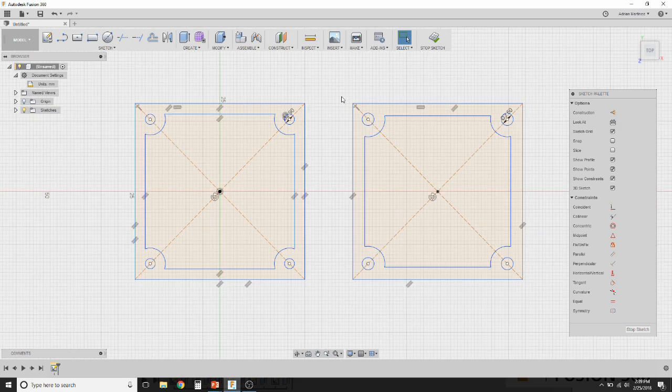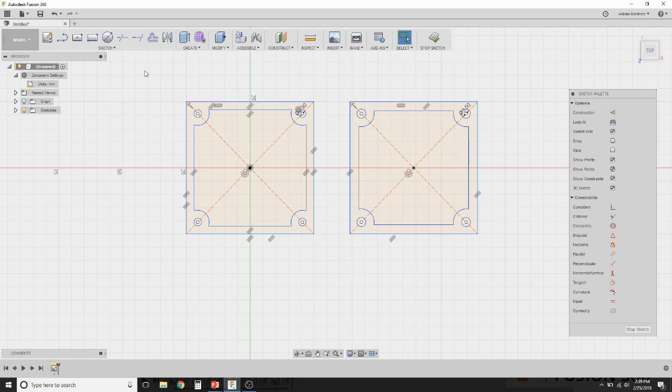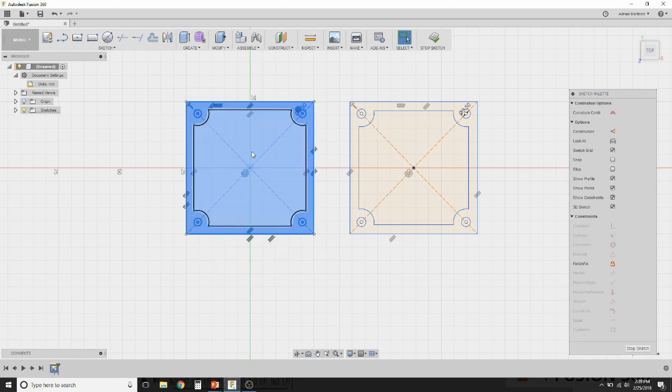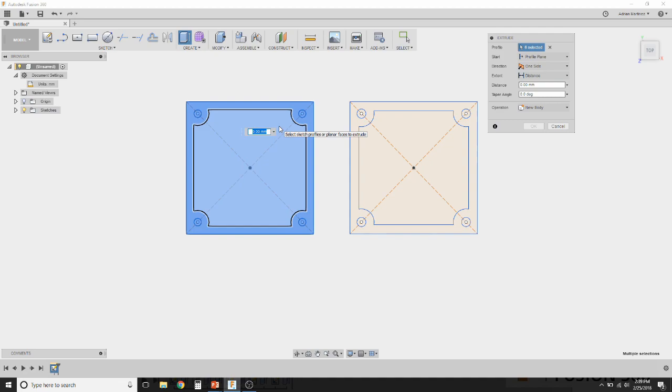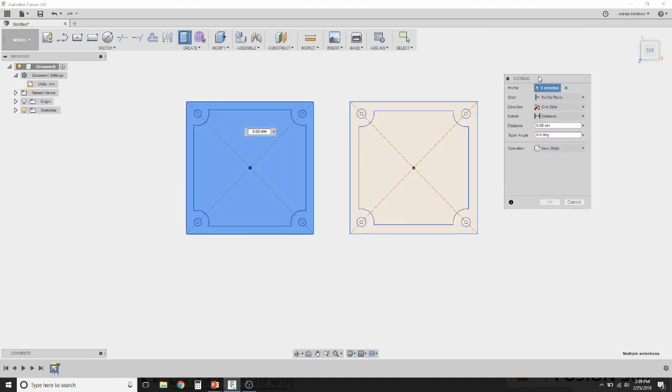Okay, now that we've got that done, let's hover away from the initial drawing that we're going to consider our box, drag across it to select everything, right click, and instead of selecting copy this time, we're going to use this tool here called press pull. Press pull gives you the ability to loft things, and it's going to activate a toolbox called Extrude. Because you highlighted everything here, by default, it'll have the 6 items selected.